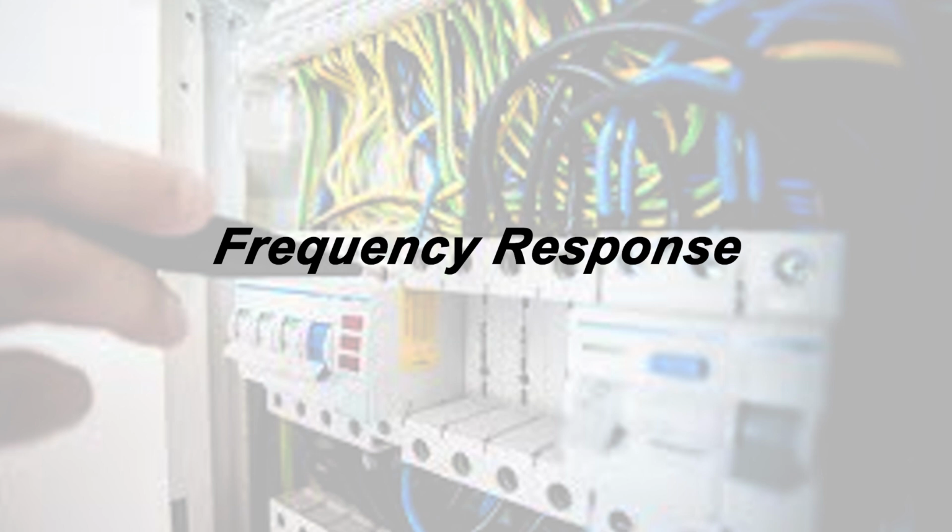Frequency response: assess the frequency response of the amplifier. This involves analyzing how the amplifier's gain and phase shift vary with frequency. Bode plots or frequency response graphs are often used to visualize this information.